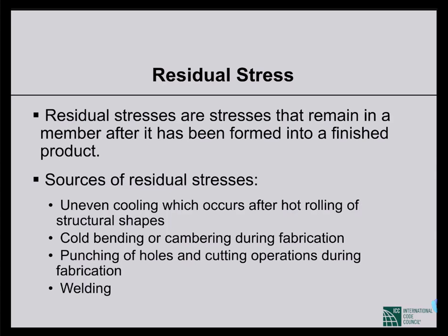Second is cold bending and cambering during fabrication. Once we bend something and keep it like that, that causes stresses to be trapped inside in those locations. Punching of holes and cutting operations during fabrication, you understand?